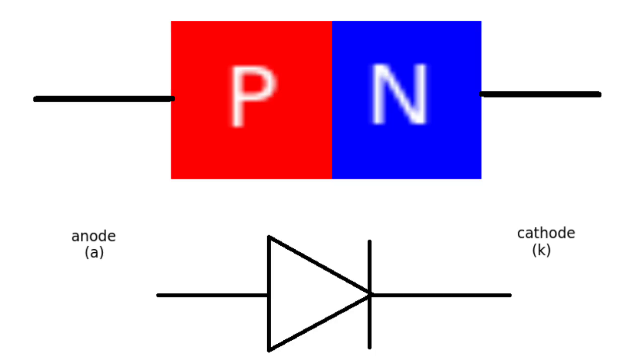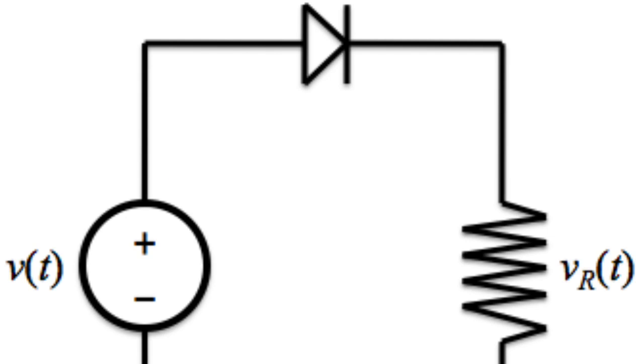When connecting the circuit, the diode is connected in series with the resistor. The resistor is used to limit the current that passes through the diode. This is to prevent the diode from being damaged. The P region is connected to the positive V bias, and the N region is connected to the negative V bias. This is one of the requirements for the forward bias.